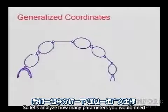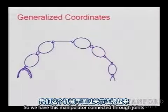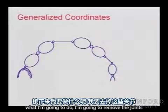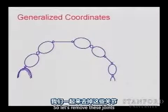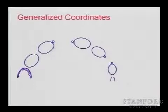So let's analyze how many parameters you would need to describe the configuration of a manipulator with a set of generalized coordinates. We have this manipulator connected through joints, and in order to count how many degrees of freedom we have, I'm going to remove the joints. So let's remove these joints. Now you have n rigid bodies in space, right?